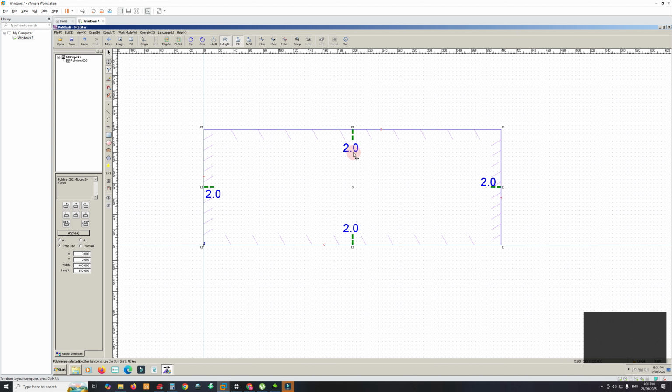Important thing to note, the reason it's important to know the clockwise or anti-clockwise is it calculates the cutting width of the jet. So if I put in my dimensions over here on the left that I want it to be 400 by 100, then this edge here is going to be spot on 100, that's going to be spot on 400. If I rotate that to counterclockwise, this inside bit now here that we're not keeping is going to be 1 mil short, because it's got to allow for the tool cutting width, the water jet cutting width. So back to clockwise.